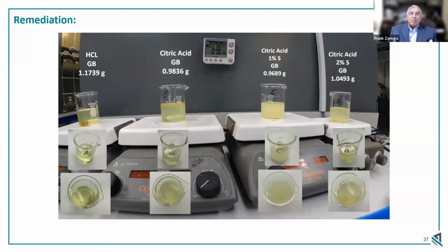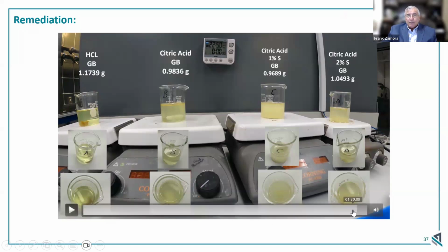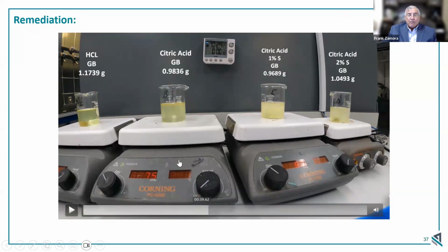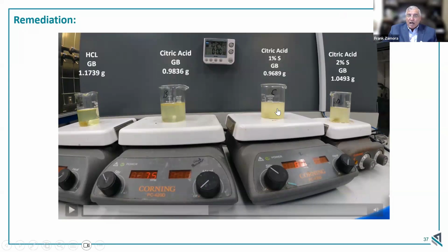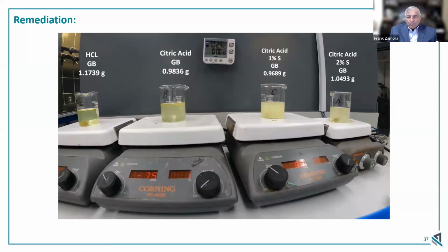Where the citric acid is a very mild organic acid. This mild organic acid is going to react very slowly on your formation. Shut the well in overnight, and over a 12-hour period, your gummy bear is in essence gone. The surfactant helps it speed up a little bit. The surfactant is helping it get to the gummy, allowing the citric acid to work and separate that gummy bear. Now, it's not dissolving 100% of the gummy bear. There's a lot of gummy bears still in solution. There's still a lot of suspended solids in here, but enough to allow it to flow out of the well.